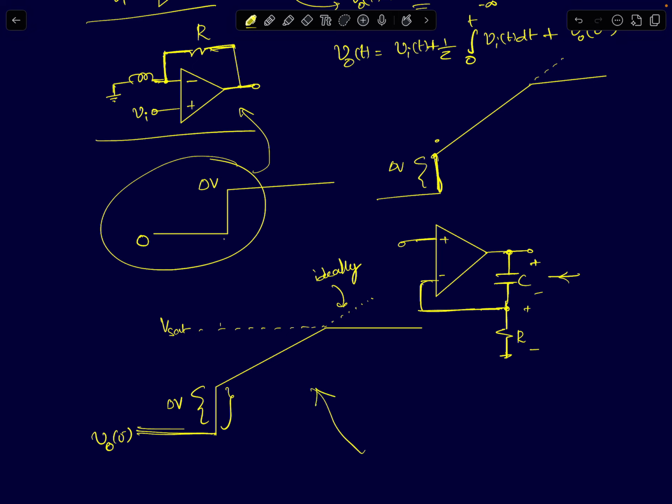The integrator circuit that we are seeing here, I've drawn this non-inverting integrator in a nice way so that you can see the output voltage of this op-amp is equal to the capacitor's voltage plus the resistor's voltage. The resistor's voltage denotes the proportional part. The capacitor's voltage denotes the integral part. The resistor's voltage will suddenly jump by delta V volts.